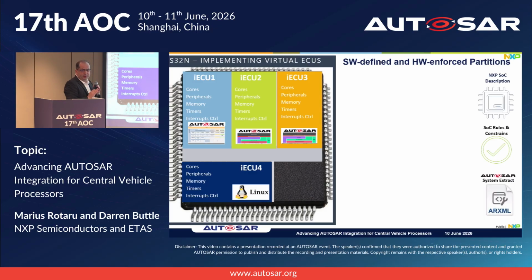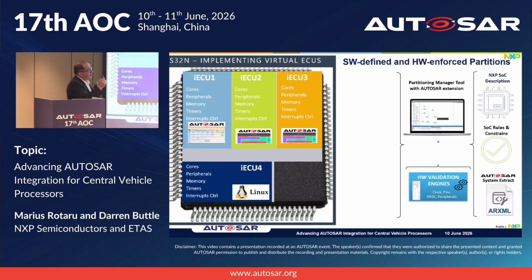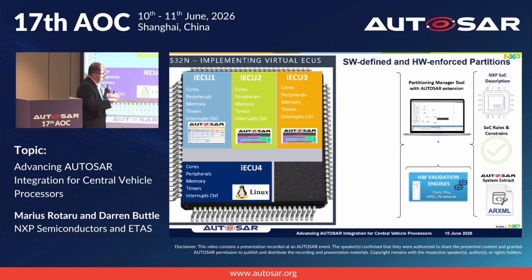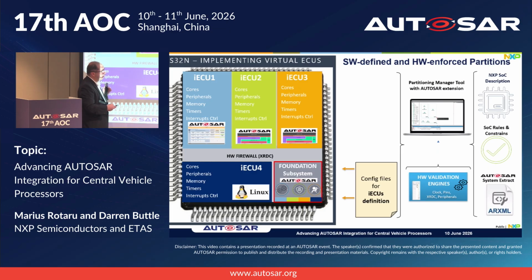Consolidation of these partitions happens without the need of any hypervisor. Taking the input to create these partitions, we provide the partition manager tool, of course with AutoSAR extension to understand the AutoSAR system extract. The tool does magic, validates all the configuration, and at the end generates a config file for the ECU definition, and we have a dedicated subsystem called foundation subsystem, which manages all the other ECUs and creates this hardware firewall.